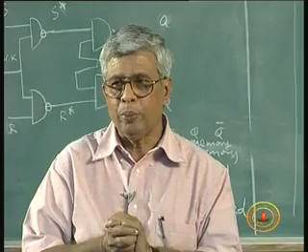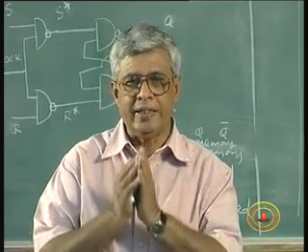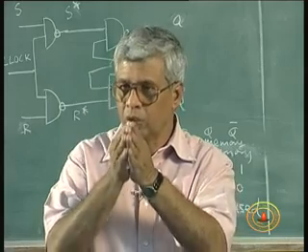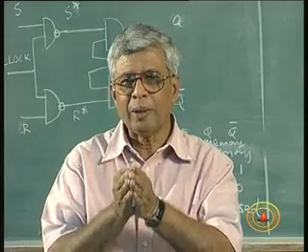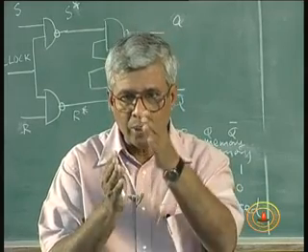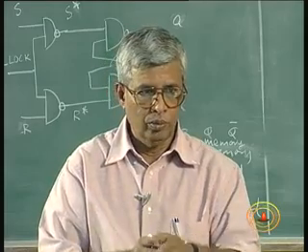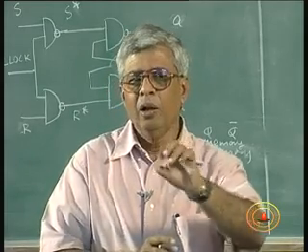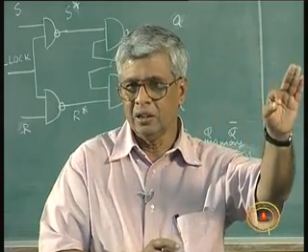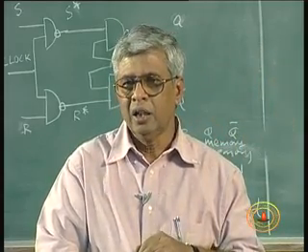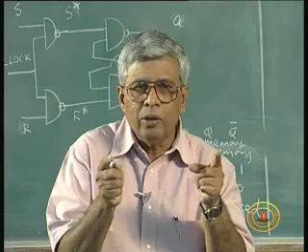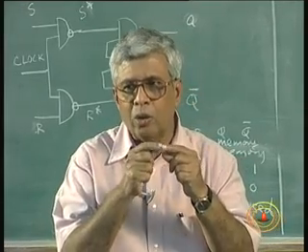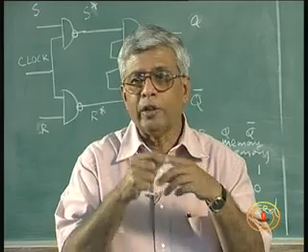So, the best way would be to make any changes into the input when the clock is low. When the clock becomes high, the values get absorbed or stored in the latch, they remain in the latch for use in the next circuit or subsequent stages, and during that clock high you never try to change the input, and again when the clock goes low, if you want you can change the input one more time.